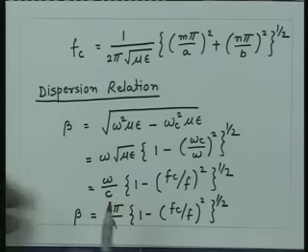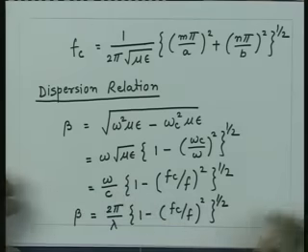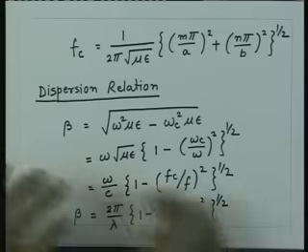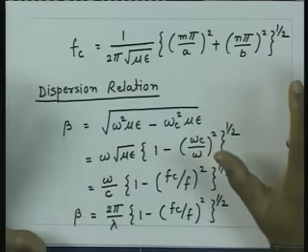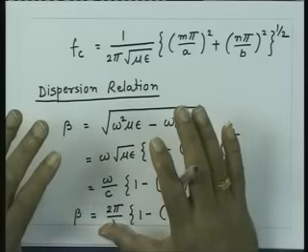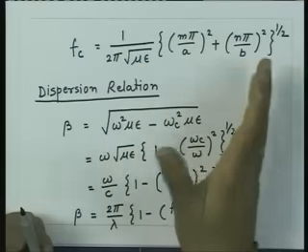Now, this is the phase constant for the waveguide in the z direction. So, now imagine that I have this structure for which the quantity which I can measure is the variation of the electric field along its length. That means, if I take some probe and move along the length of the waveguide, I will see the separation between 2 points, 2 maxima, which will be separated by a certain distance, and that will be related to the phase constant of that wave along the direction of the waveguide.